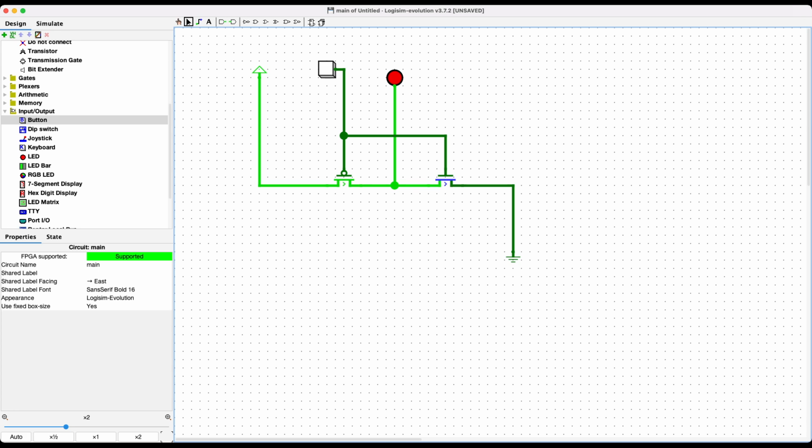So we have two transistors here. Those are the little thingies, one above my mouse cursor, and then this other one that's got the little loop on it. Those are MOSFET transistors, a different type of transistor, and they come in two flavors, NMOS and PMOS. NMOS is this one. PMOS has the same symbol, but with this little loop on it. The way these things work is they're essentially voltage controlled switches.